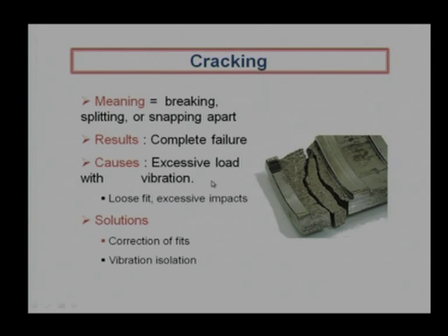This majorly happens with excessive load, but here, in addition to excessive load, vibration is also there. Vibration of the reversal load is there, or some sort of impacting, and then this kind of failure will occur. When we are talking of vibration, we are talking along with a loose fit. If there is a firm fit, vibration will not affect the results, but if there is a loose fit, vibration is going to impact again and again. The way we understood erosion, where individual particles were there, here the whole metal will impact with a much larger velocity and larger impact energy.